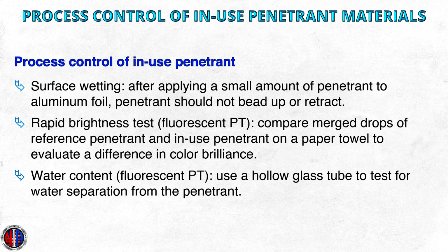Rapid brightness test for fluorescent PT. Compare merged drops of reference penetrant and in-use penetrant on a paper towel to evaluate a difference in color brilliance. Water content for fluorescent PT. Use a hollow glass tube to test for water separation from the penetrant.